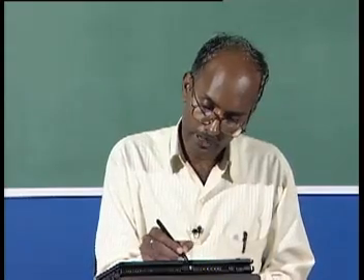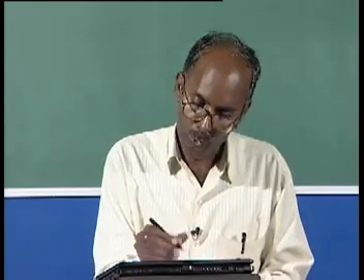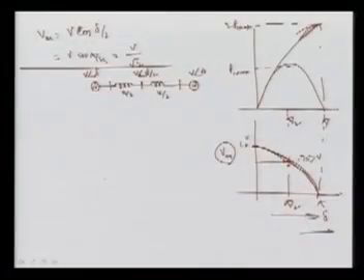So this midpoint voltage magnitude we are just fixing to V, but the angle will be half, and this value is x by 2, this is also x by 2, and now we want to derive the power. The power flowing in any section will be equal to the power in the other section, so either you can write for this section or this section, immaterial. Let us write the power for this section, between this voltage and this voltage.